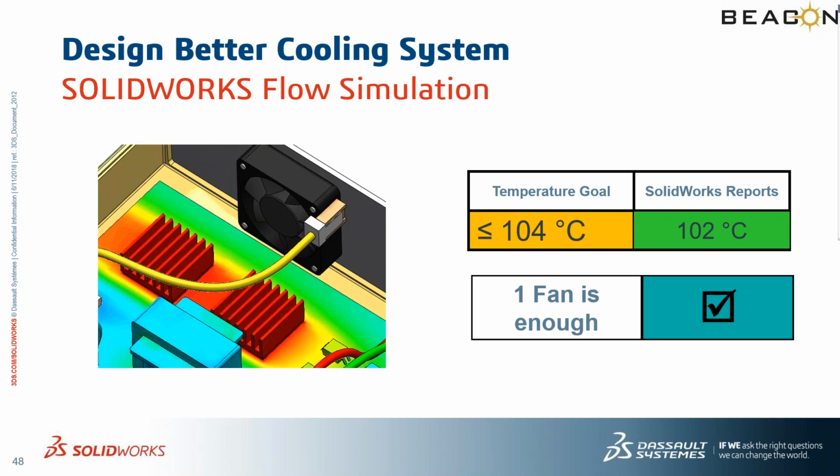Now, coming to a conclusion, this particular heatsink design with one fan at the middle of both the heat sinks can give me a temperature of around 102 degrees centigrade, which would be the best combination I could find according to the configurations, the heatsink designs and the fan locations I have.